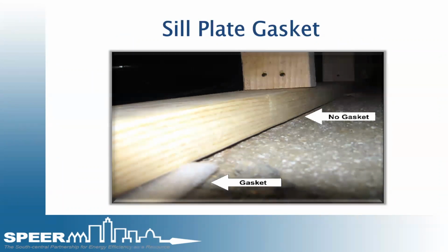So where the two meet, there's always gaps there. A lot of the builders do use poly seal on the inside on that gap. A lot of times it's either scraped off when the flooring is being installed, or if there's some expansion and contraction during construction, that poly seal can actually pop and open that gap again. But having that gasket placed there on all exterior walls, even including the garage wall, is ideal to have that moisture stop installed for air intrusion. So it must be included.